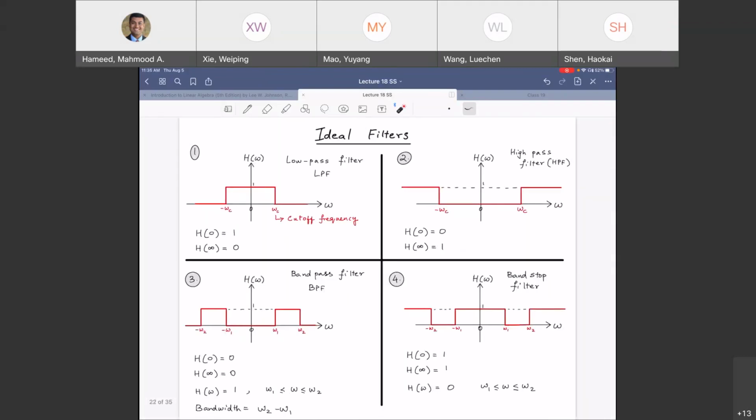So essentially, where should my poles be, right? What this topic will allow us to do is, I can design my own system. You just tell me what type of filter you want and what is the bandwidth, what is the cutoff. I will be able to tell you where you should put the poles, right? Where should you put the poles so that you get a low-pass filter? Not an ideal one, a Butterworth one, so a realistic one. Should be stable, of course. So right away, you know that the poles are going to be in the left half.